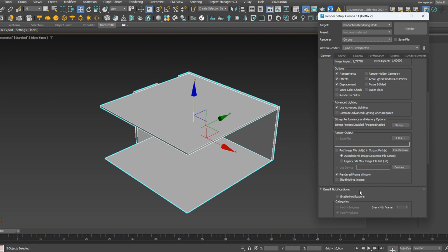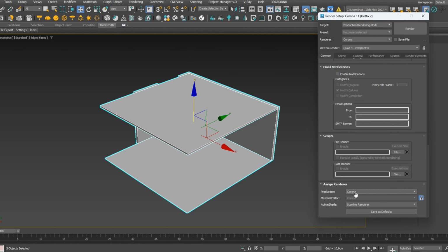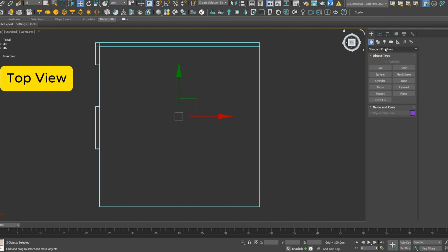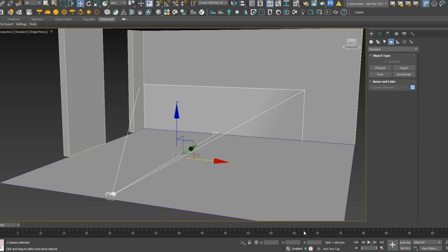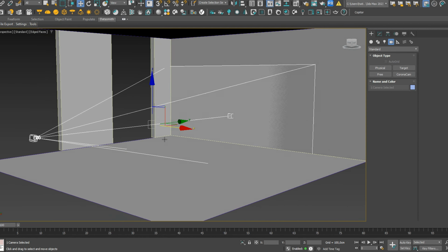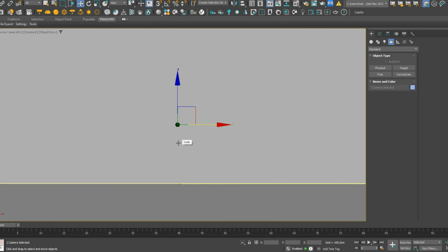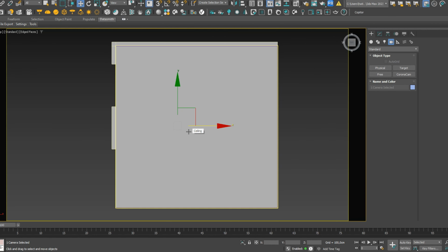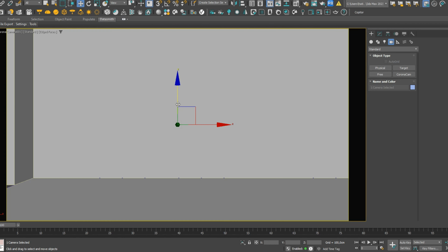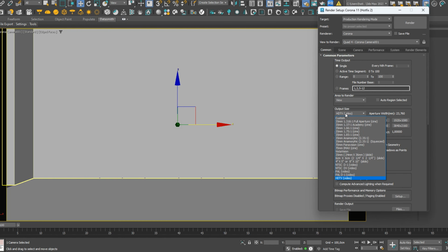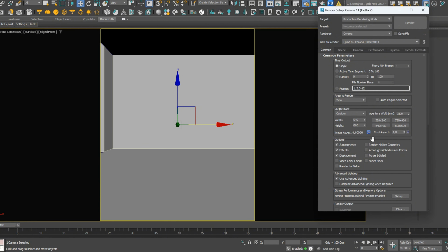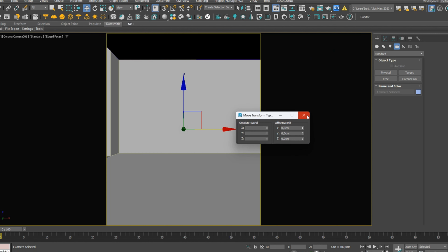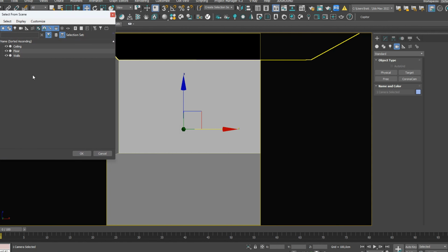At this point, I checked if my render settings were set to Corona by using the shortcut F10. Then I added a Corona camera to my scene. I placed it 1 meter above the ground. I adjusted my camera angles. Then I set the Instagram ratio to 1.8 for the post I'm going to share on Instagram, and I locked it. I did the general camera settings from here.